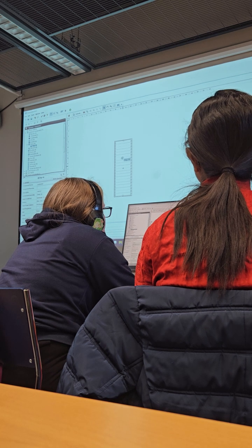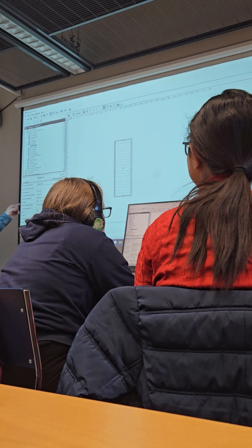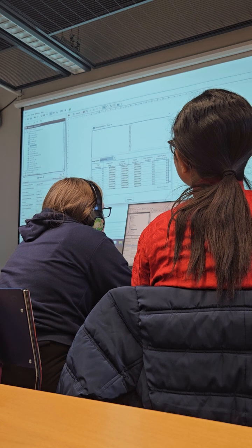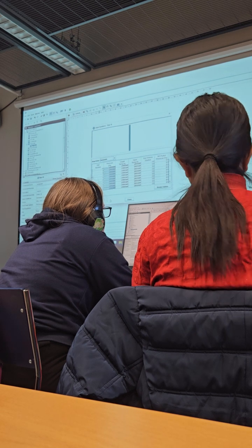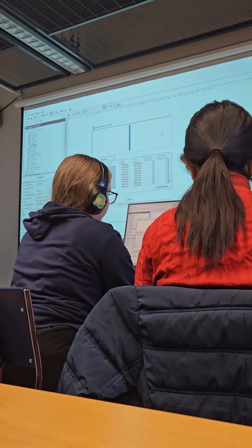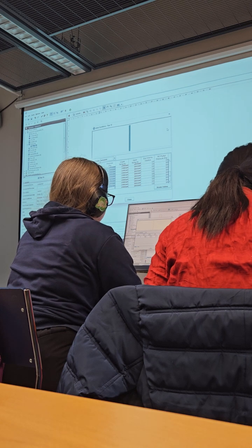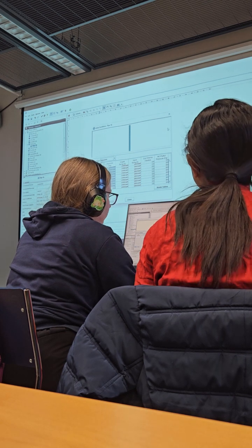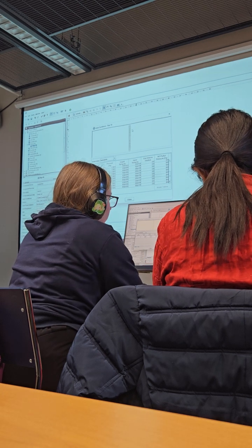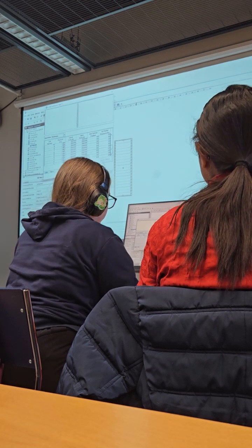And what we can immediately do here is put in the initial conditions, which are in red there, and we can check that for the boiling water case it was 70 bars, so that is 7e6, which is 7 megapascals, and for that it immediately gives me the saturation numbers here.